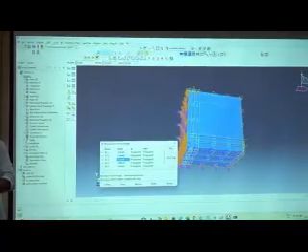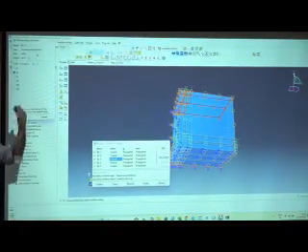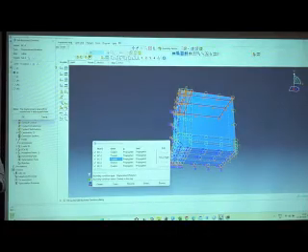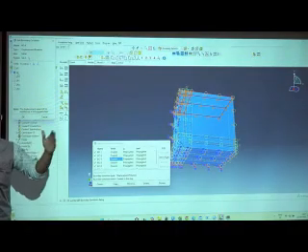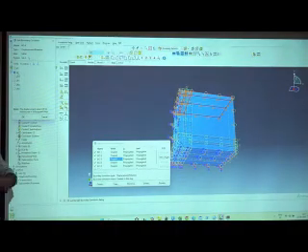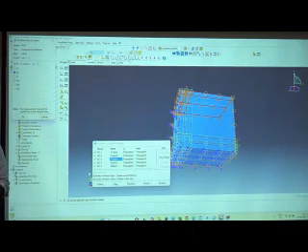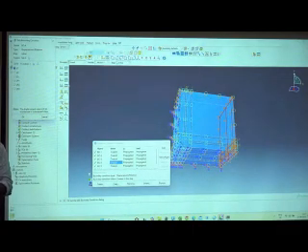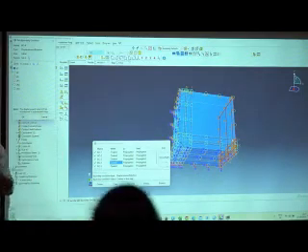This is the displacement option we have. In y, U2 means the displacement is not allowed in the y direction, so it is simulating the other part. Similarly, on this part, the translation is not allowed in the x direction.